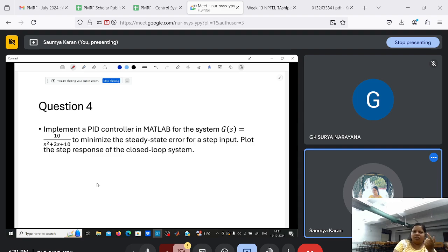Then this PID controller is tuned according to our system to achieve a good level of performance. So you get Kp, Ki and Kd values to be this for our system. Okay, so this was really easy. And when you have this PID controller, you can analyze the step response. So I'll run this.